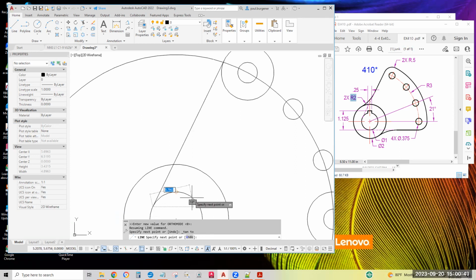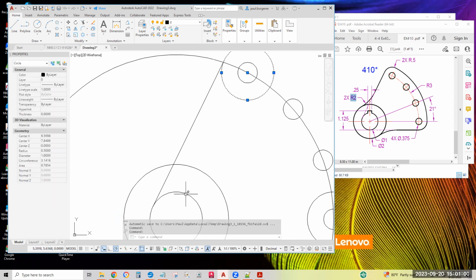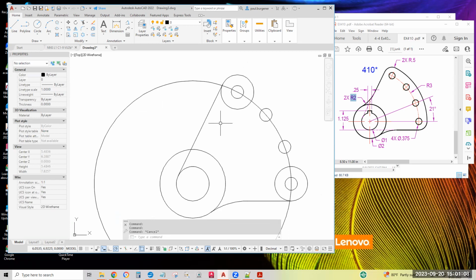And I believe because these circles are identical, it does hit at that intersection there. By coincidence, this circle and these 2 circles are both radius of 0.5, shown in properties. Hit escape to deselect. I'll put the fillet in here again, the same way I did down here. Click fillet. The radius setting is already 2 units from the last time I used this command, so I don't need to change the radius setting.